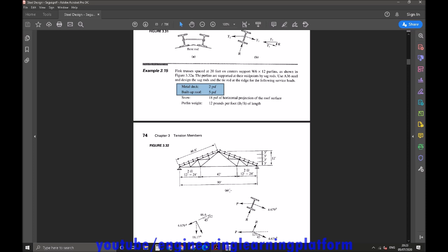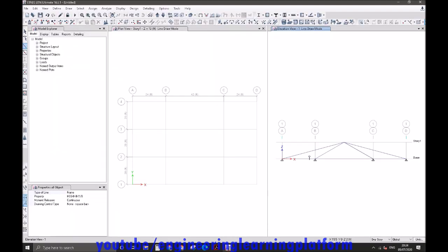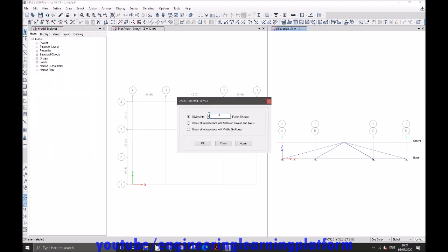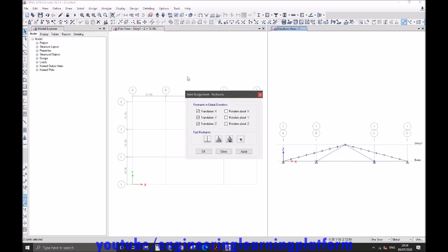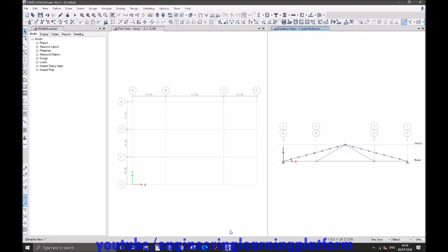So this is a perpendicular member connecting to the purlins line. I suppose we would require to add the purlins first at the specific spacing that is provided. There are 8 spaces between the 9 purlins, so we have to divide the line into 8 spaces. So we get 9 points where the purlins would lie. Remove these supports as there were no supports present here initially.